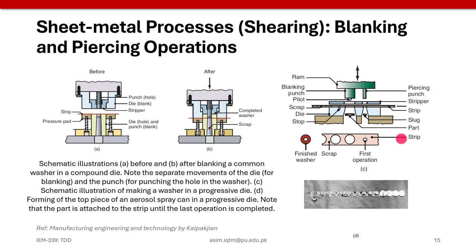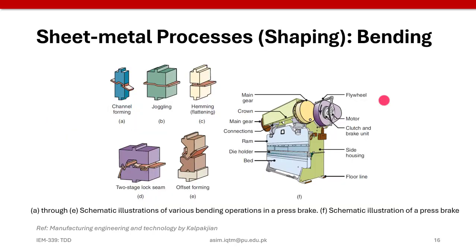So combining those two operations in a single die definitely reduces the design cost based upon the production cost of dies. Definitely first you design the die which is helpful to produce the part, and if you separate these two processes into two kinds of dies, then definitely you have to put extra energy into producing those two different types of dies. So again, designing of dies is important.